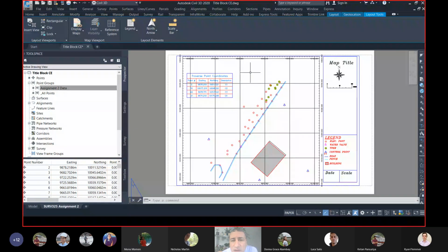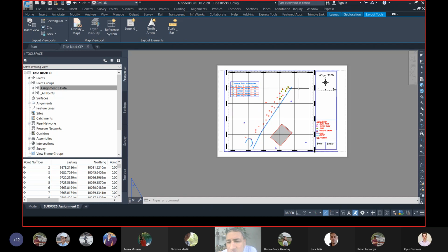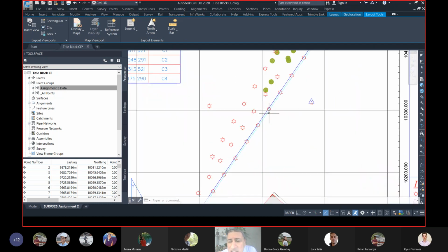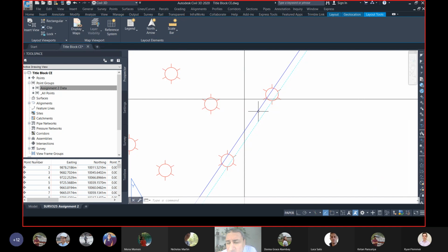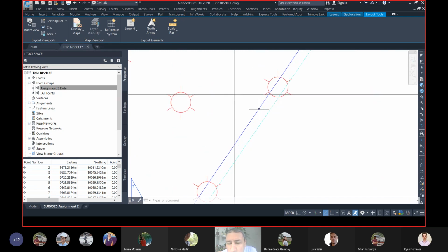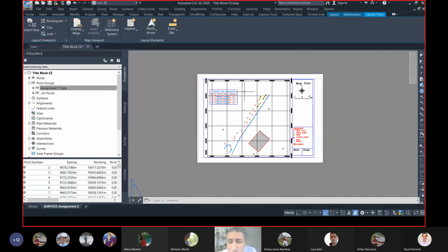They should be very light. Okay, so because they should be very light, what happens? We control this through bin assignment or plot style. How do we do it? Simply we look at the color. For example, the color is white, like this is number 7 in CAD, and in my bin style I make this very thin. While something like the road edge, like this blue here, I will make the blue a heavy color, like thick, so this will print thicker on your map. That is how we make our map beautiful.